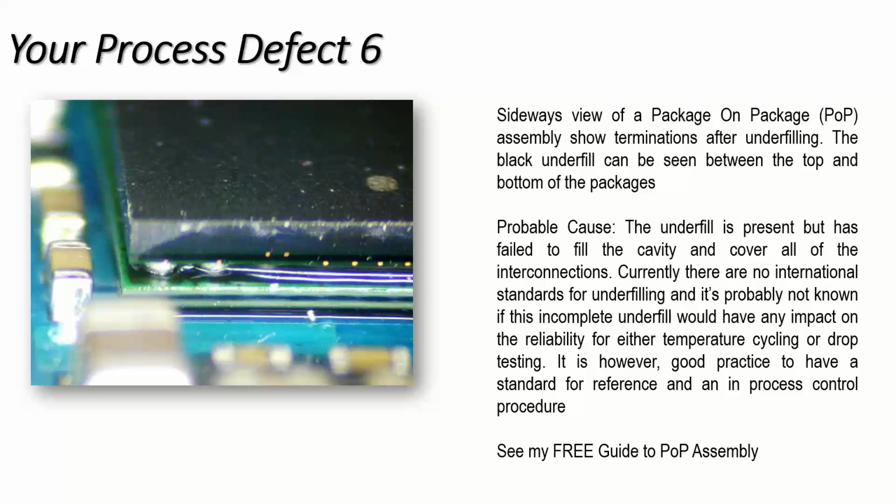They're exposed, they're visible. Now, the problem here is that we haven't put enough underfill onto the package, so when it's capillarying underneath, you've filled the gap, but there isn't enough to actually cover all the way around the package.